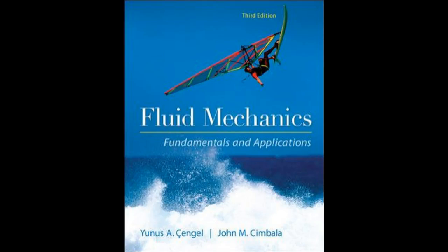4-6. The Reynolds Transport Theorem. In thermodynamics and solid mechanics, we often work with a system, also called a closed system, defined as a quantity of matter of fixed identity. In fluid dynamics, it is more common to work with a control volume, also called an open system, defined as a region in space chosen for study.